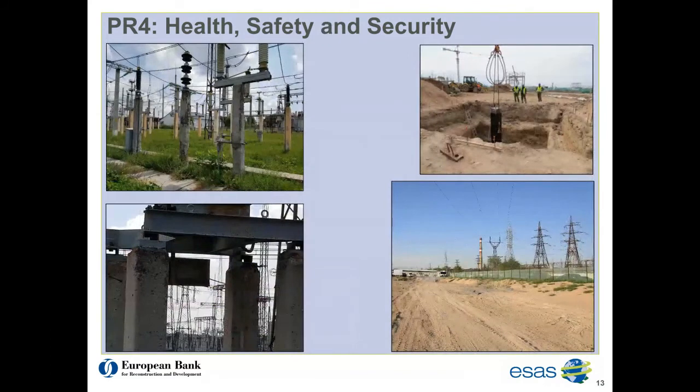During the site visit, the following observations were also made. The concrete supports and poles are heavily deteriorated, and phase and conductor brackets are heavily corroded. Stability and structural integrity needs to be considered, assessed, and the working method adjusted for the removal of conductors to avoid pole or support failure due to change in structural load or forces.